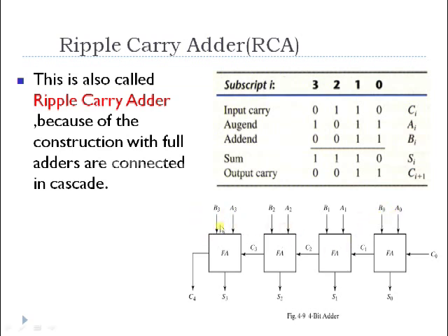Now all these inputs are given directly, at the same time, to 4 full adders. Along with these inputs we are giving one carry, and that carry is 0, because the initial carry would be 0. Therefore I would get the outputs S0, S1, S2 and S3. C1 is the carry output which we get from the full adder circuit, and that is given as an input to the next stage. In the same way, you will get the final carry as C4.